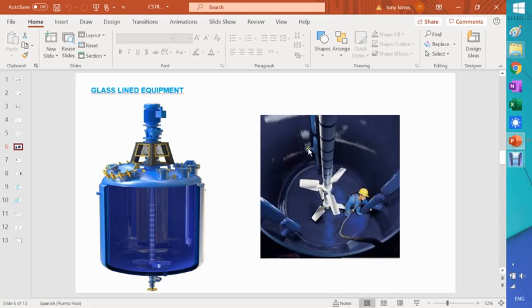And sometimes you have to get into this vessel to ensure that the glass lining is correct. Sometimes you do that with high voltage discharge just to ensure that there's no tearing within the glass-lined vessel, things of that nature. That used to be done during shutdown. We run through the whole year, and there were a few weeks here and there where you have the opportunity to do a good check on the vessel integrity.